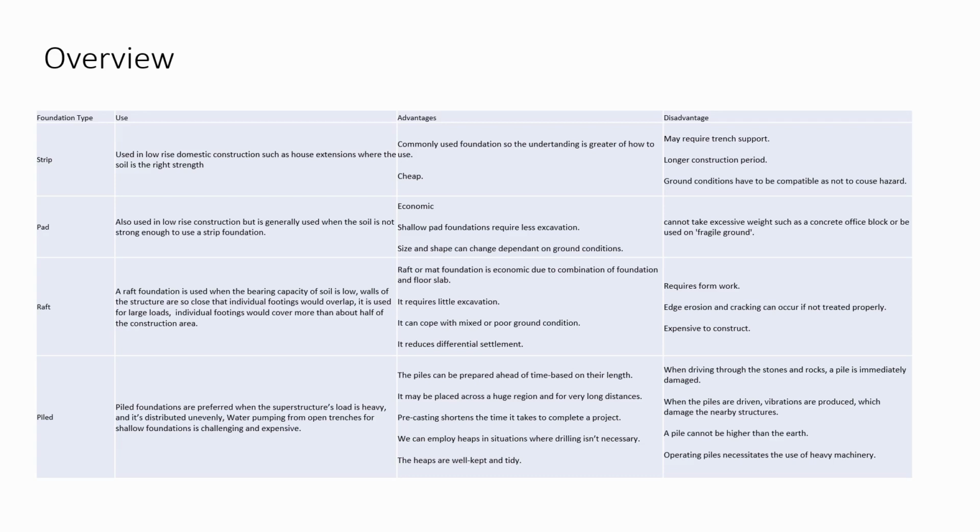Lastly, the pile foundation can be prepared ahead of time based on the length. It may be placed across a huge region and very long distances. Precasting shortens the time it takes to complete the project. We can employ piles in situations where drilling isn't necessary. Unfortunately, when driving through stones and rocks, a pile is immediately damaged. When the piles are driven, vibrations are produced which can damage nearby structures. A pile cannot be higher than the earth that it's in, and operating piles necessitates the use of heavy machinery.